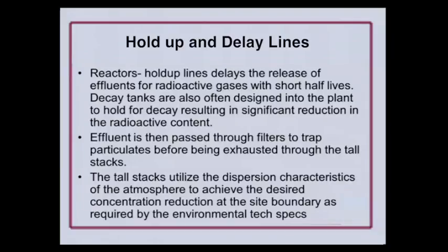The effluent is also sent through filters, just like it would be in a liquid system, to catch any particulate that may be entrained, because as best as you try, you're going to get some corrosion of the piping system that may get residual radioactivity on it and get caught up in the air, and so there will be filters installed.